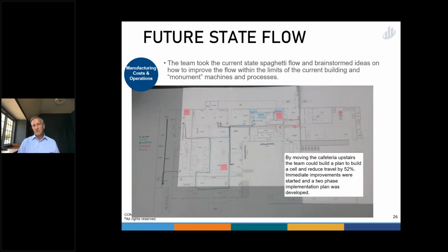That same milk run also returned products from all of those cells to shipping and/or the warehouse. The Kaizen event that was identified to develop this milk run concept and create stations for dropping off, doing transactions on inventory, and picking it up reduced the need for material handlers by 60%. And those people were redeployed to other functions.